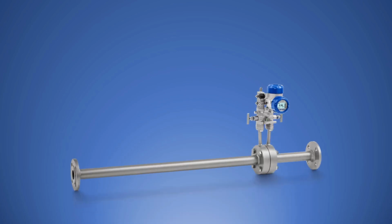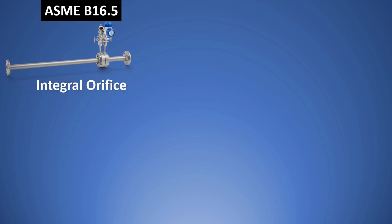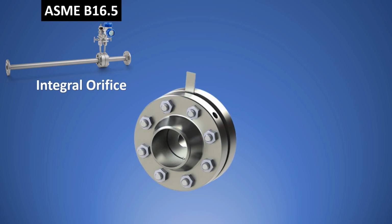Finally, this amazing standard also covers flanges. Imagine this is hypothetically your integral orifice. This is all given by the vendor, and these two flanges are where you need to fit your integral orifice. Now these are normal flanges, right? For this case, the standard that we would be using is just ASME B16.5, which is the normal standard. But a special standard is made for orifice flanges because holes are drilled into them.